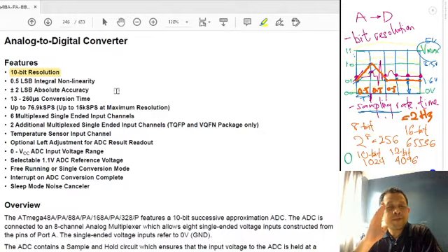So more than 8 bits, you have to go to the next byte and use the full byte. Which means that for 10 bits, you need 2 bytes. So for the ADC built inside the ATmega, you need 2 bytes to store a single conversion of the ADC.